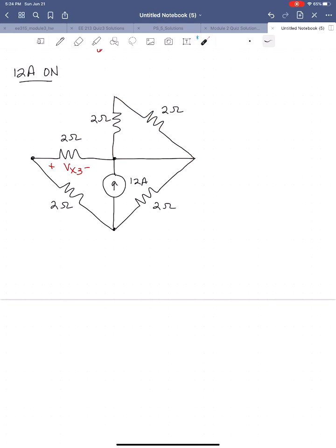What that means is that this 4 ohm series combination is connected in kind of like a circle, and current's not going to flow like that. It can't flow back through a node in a different direction than it started with. So the 2 and the 2 are shorted out, and we don't need them. They don't contribute to anything. So I'm going to go ahead and just take these out.